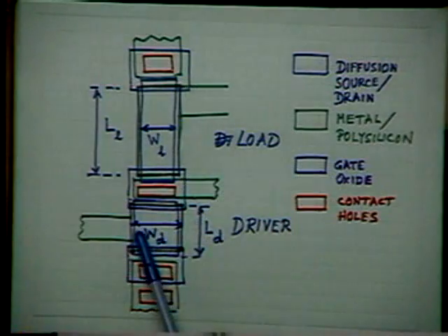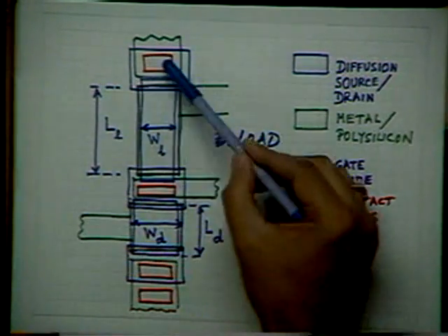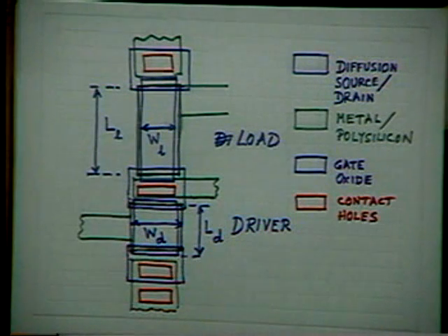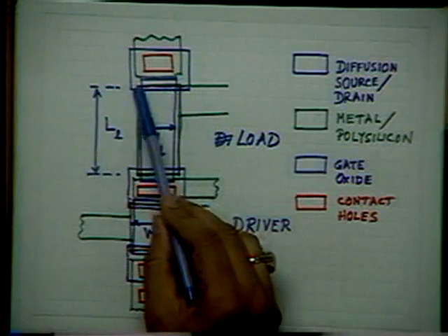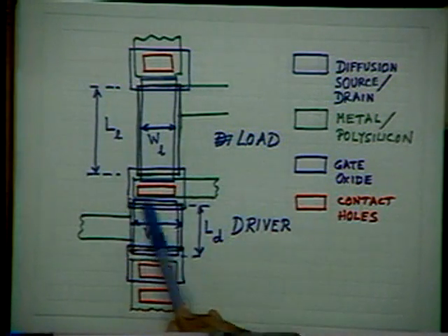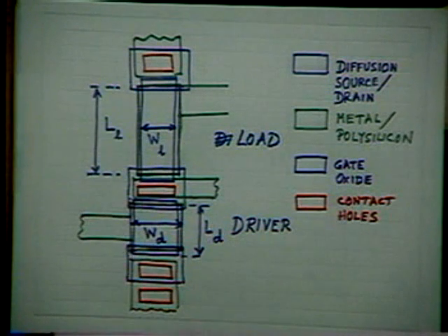region of silicon which overlaps the diffusions. You just see that this has overlapped these two diffusions. Similarly, this has overlapped these two diffusions. They represent a region of silicon where thick oxide has been removed and a very high quality thin oxide called gate oxide has been formed. This is very important. After that, this green rectangle here and this green rectangle here indicate the gate electrodes.